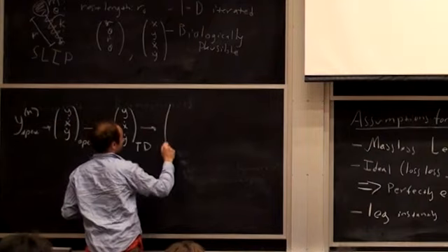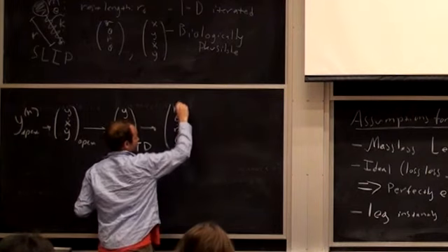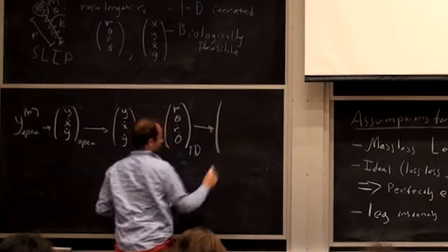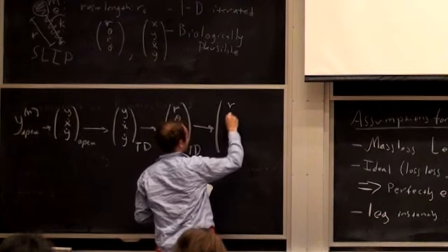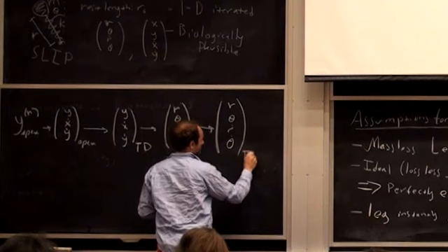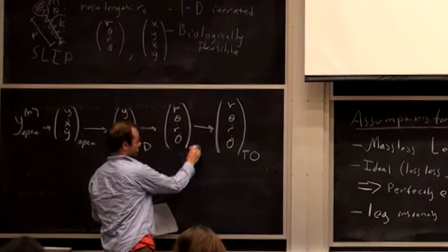Now we have to change our coordinate system to r, theta, r dot, theta dot. This is still touchdown. And we swing that through in the stance phase, and we get r, theta, r dot, theta dot at takeoff. So my d and my o are as different as I can make them look.